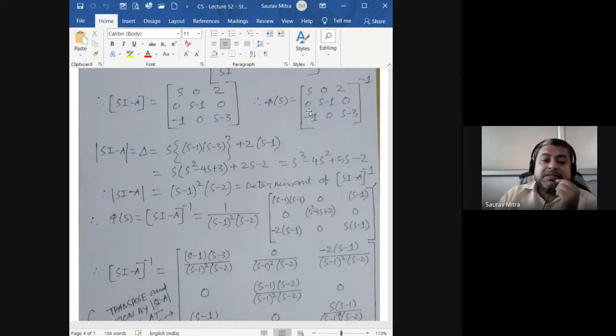It is called the state transition matrix, required while finding the solution of any state variable differential equation. This is the significance. So without finding sI minus A inverse, or without finding phi t, we cannot go anywhere in state transition matrix. So this is a must step for all the numericals in state variable analysis.